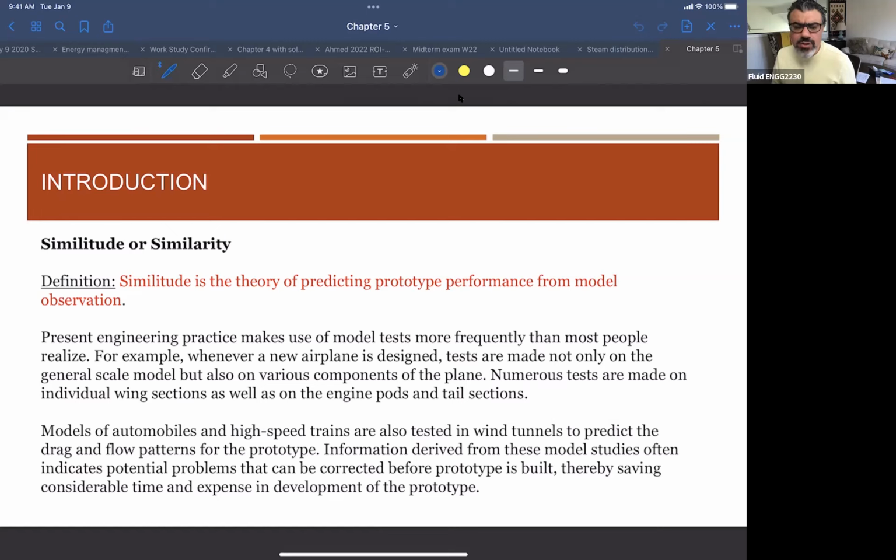Maybe the analytical model that you have, you don't know exactly. Navier-Stokes equation has a lot of assumptions, right? I like you thinking about that. So Navier-Stokes equation, computational fluid mechanics, has a lot of assumptions. Even though you think you are modeling every single particle of the fluid movement around the car, you still have to calibrate the computational code, right?